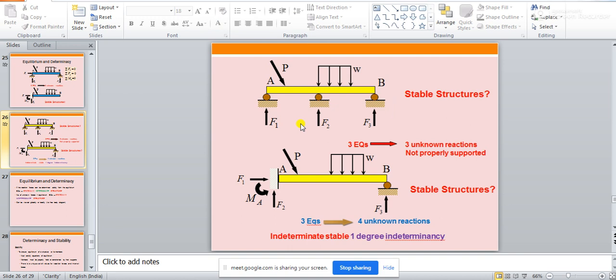So you forgot engineering mechanics in that case. What I have said: if there is a parallel force system acting on a structure, and there are no other forces coming, then the structure will not be a stable structure. Just try to understand from the very basics. See, there are 3 rollers on this, right? So rollers can have only vertical reactions. They cannot take any horizontal reaction, right?